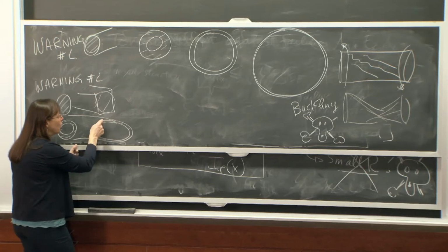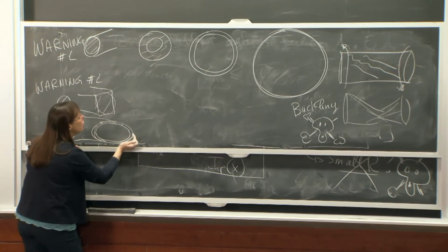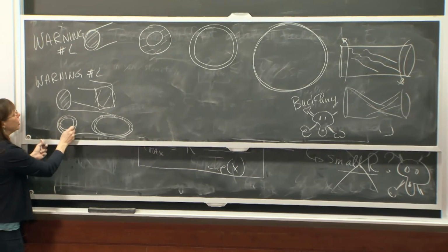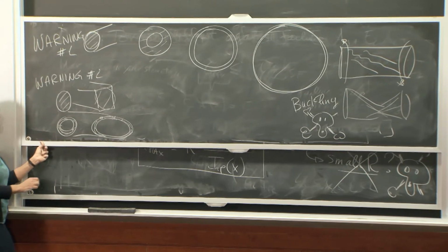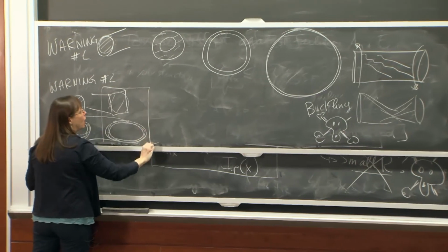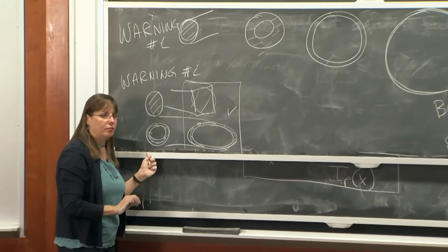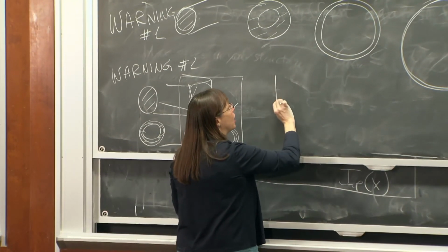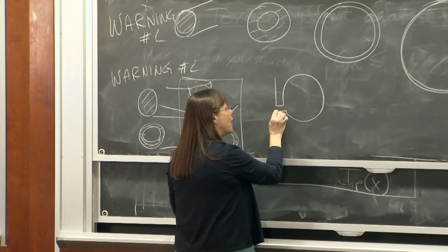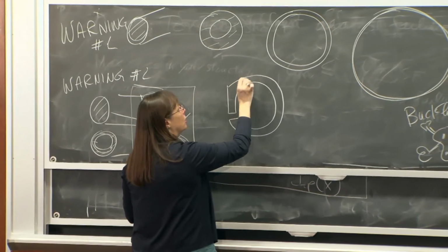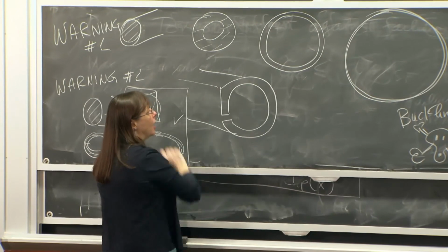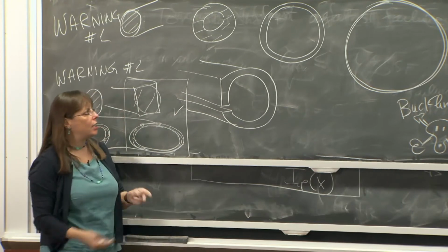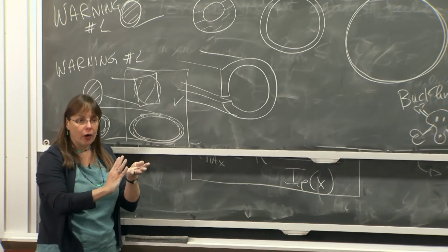If you have something thin, there are going to be stresses flowing around the thickness of the wall, just the same as the stresses flow around your little round shaft. So this part is different from 201, but the concept is kind of okay. The things you have to be worried about are things that look like that. If you have something which has an open section like this and you put it in torsion, they're horrible in torsion.